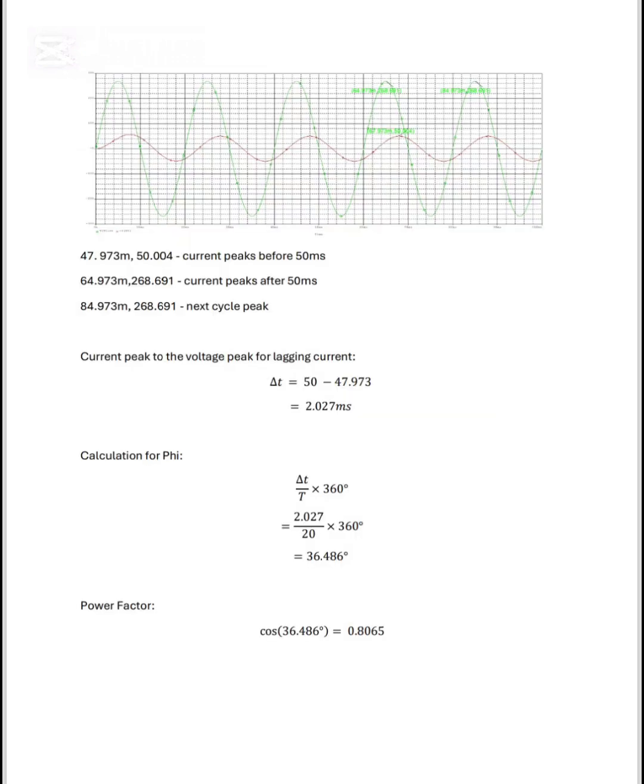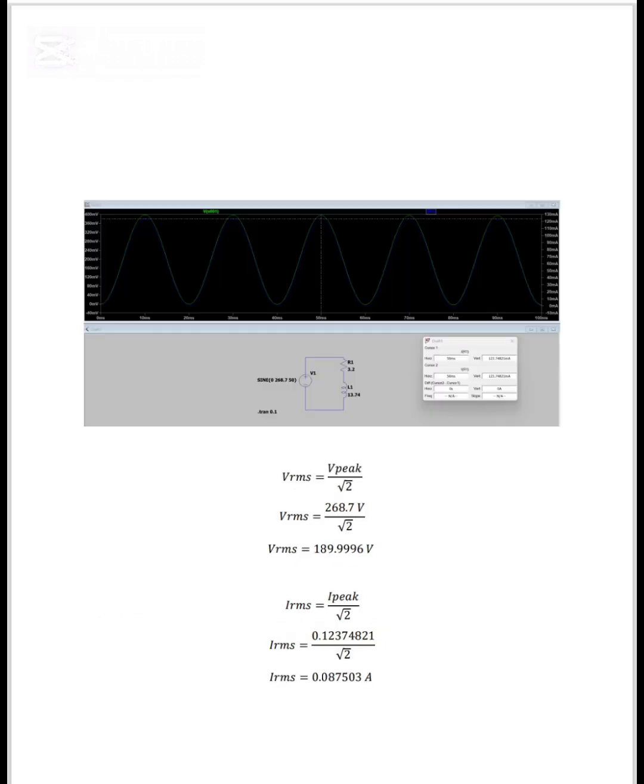Power factor correction, or PFC, is the process of adjusting the power factor so that it is closer to 1, or unity. It is usually done by adding capacitors to a circuit that contains inductive loads. A low power factor means that a higher current must be drawn to produce the same amount of useful work, so a lot is wasted. This causes greater energy loss in cables and can sometimes lead to penalties from electricity providers, so you are paying for more and getting less.